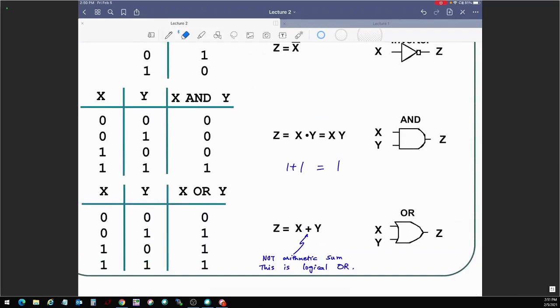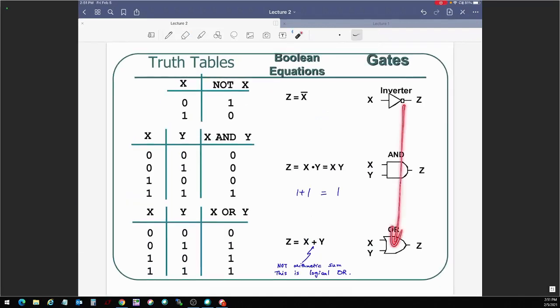Let's take a look at some of the symbols here, because symbols are very helpful in order to, again, express a logic function, right? So remember, just a few minutes ago, I said there are many different ways of expressing a logic function. The most unique way of doing it is to use a truth table. But other ways of doing it, which actually are not unique, are Boolean expressions or binary expressions or logic expressions, and symbols drawn up one after the other, connected using wires. That's a logic diagram, right? So a logic diagram can also express a logic function, but it doesn't do that uniquely, right? You could have many different ways of drawing a logic function. So we'll take a look at all these ideas that are coming up later.